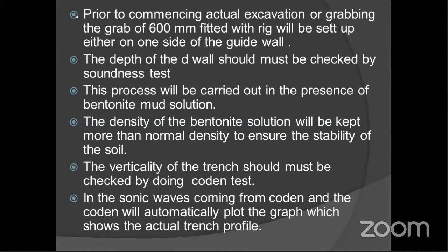And suppose if we have reached our depth of the D wall, how are we going to do the soundness test to check the depth of our D wall? So we will go for the soundness test. In this test, we are going to put some heavy weight, connected with a chain, and we'll be inserting it inside the D wall, so that when it touches, we will observe or feel some sound, and with the chain length we can calculate the depth of the D wall.